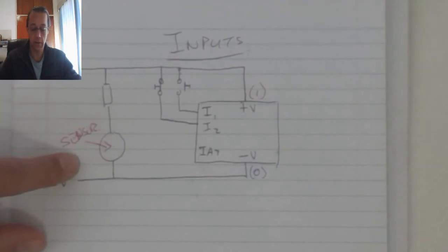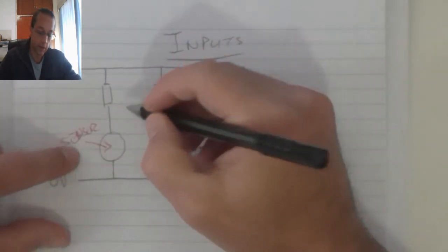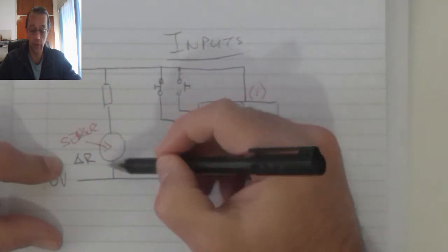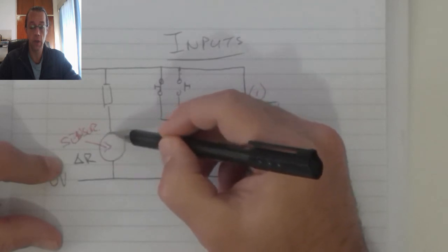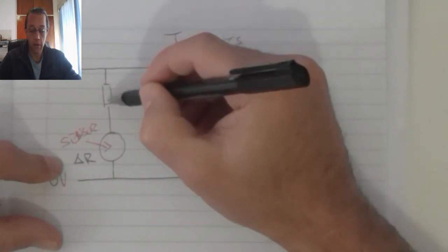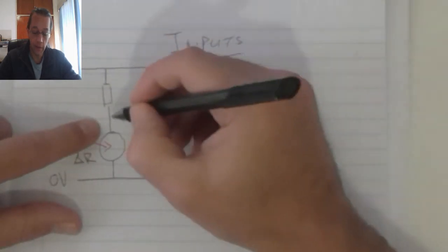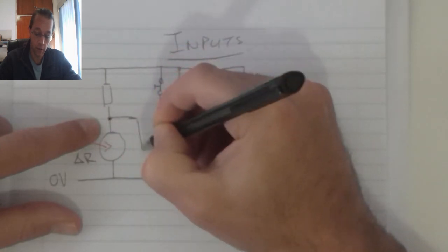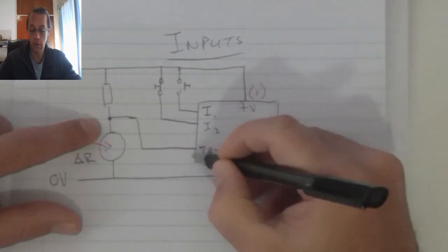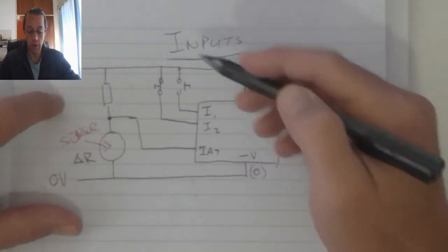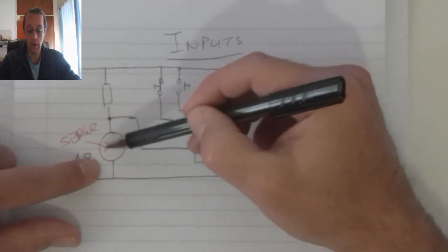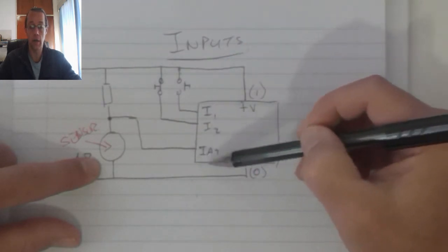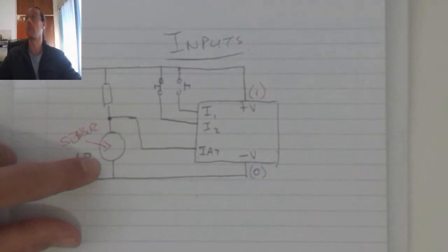Typically the sensor is a device that changes its resistance in accordance with the voltage or its value that it is measuring. It's connected in series to develop a voltage divider bias, and then that connecting point between the sensor and the resistor will connect to my analog input. So as the sensor changes its resistance, it's going to change the voltage across itself, and that is what my analog input is going to measure.